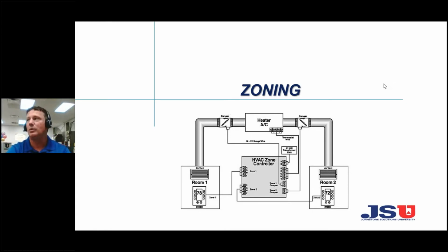So last week we were talking about static pressure and the effects of static pressure on systems, especially as they pertain to different blowers that we're working with, whether it be PSC, an ECM constant torque based, or a true ECM variable speed. And we have different consequences because of poor ductwork and because of high static pressure.